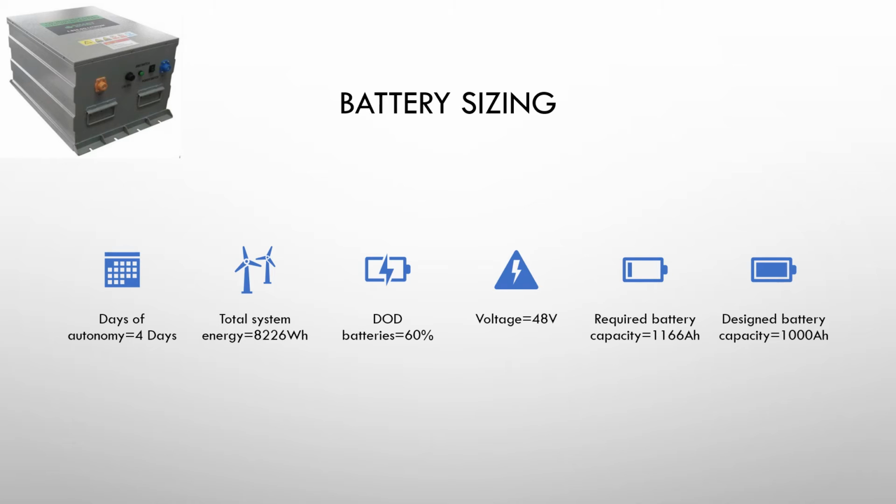While the capacity of the batteries is slightly lower than the required battery capacity of the system, I'm satisfied with that since the battery has 3.43 days of autonomy, only slightly less than desired. This isn't a huge flaw, since I decided long-term cost efficiency was the most significant factor for the system design. The 8 batteries cost a total of $40,000 at $5,000 per battery.